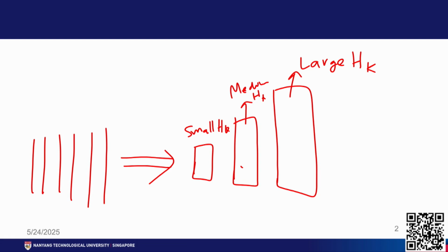Okay, so, this way you can switch even materials with a large anisotropy field more than the field that can be produced by a writer. Okay, so, this is the concept of incoherent switching. So, this is one reason why we have many recording layers.